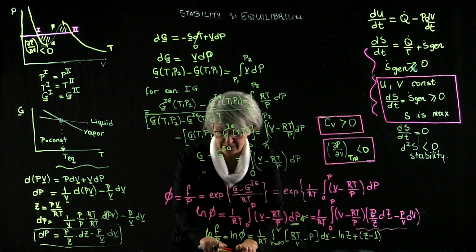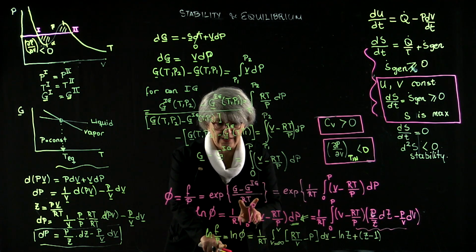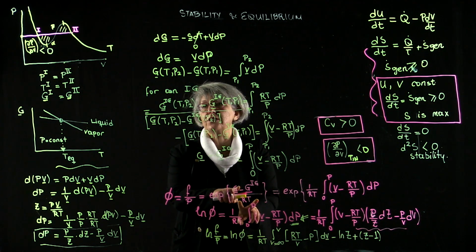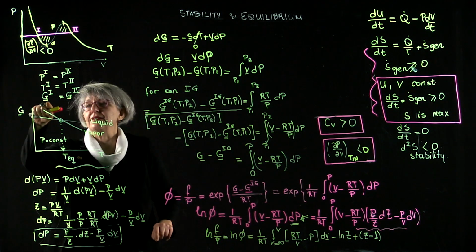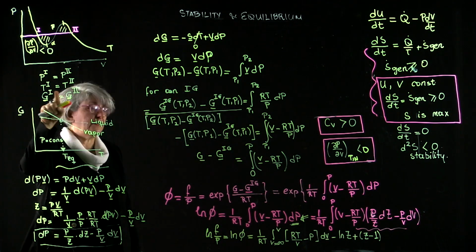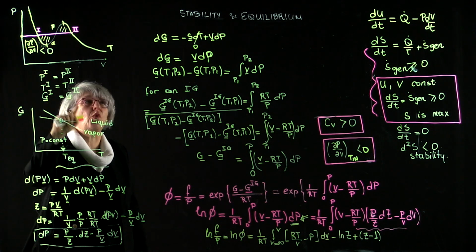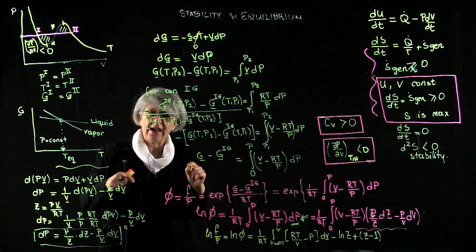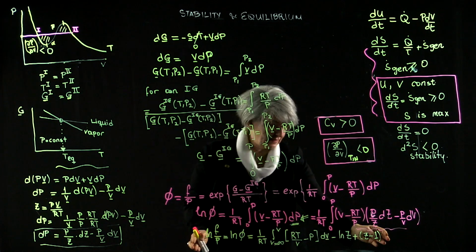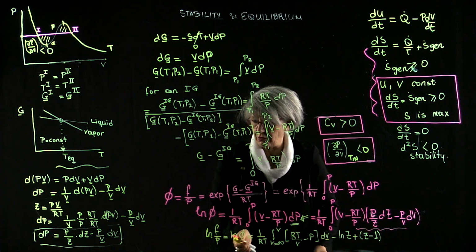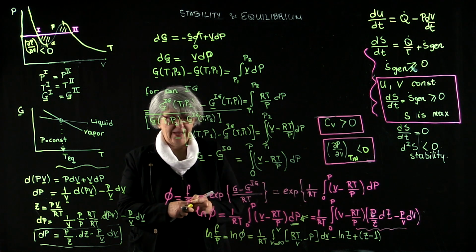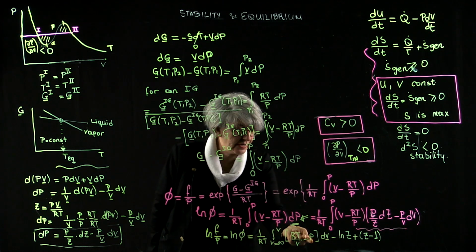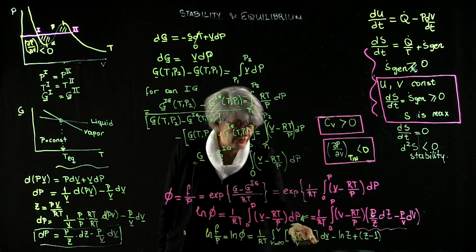Now this final function is an implicit function of the Gibbs free energy. As a result, instead of the equalities of the Gibbs free energies, which requires us to go through the entropy parameters, we have an equation here which represents the fugacity coefficient of the fluid, and that equation can be estimated using an equation of state explicit in volume.